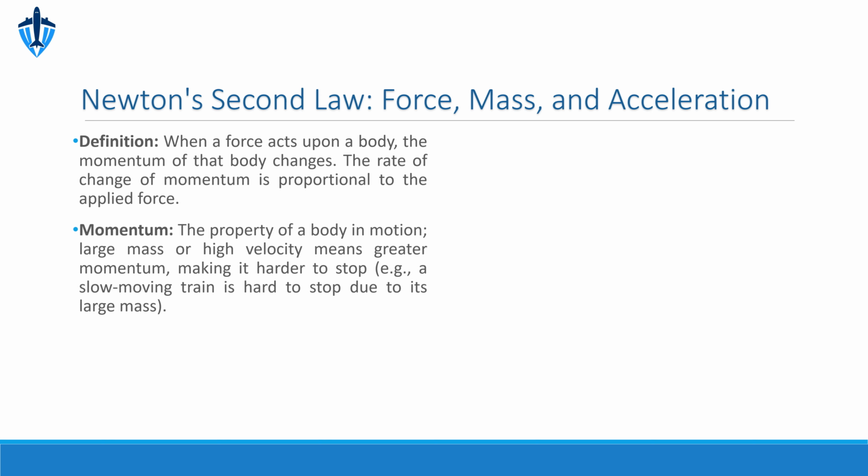Finally, we have third-class levers. These levers have the fulcrum at one end, the resistance at the other, and the effort applied in between. They are designed to increase the speed or distance of the resistance even if it requires a large amount of effort. A good example is the retractable landing gear on an aircraft, where the top of the gear acts as the fulcrum, the wheel and brake assembly is the resistance, and the hydraulic actuator in the middle is the applied effort.